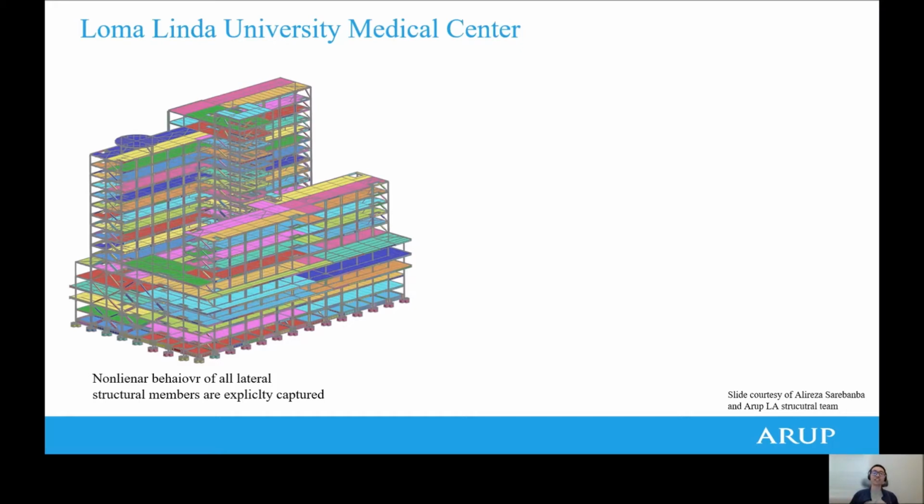The BRB braces are also modeled explicitly. Effects such as kinematic hardening can be captured, and the connections are modeled with constraints and special treatment to mimic the rigidity, and slabs are modeled with shell elements to provide expected rigidity both in plane and out of plane. One of the important parts of the model is the isolation system.